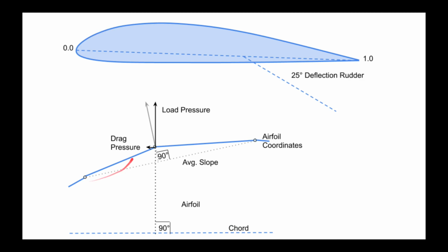And so that's what these little circles are representing, the positions of the individual points on the airfoil, and that would be something like up in here. And those pressure values we have are at those coordinate points. Like, for example, this gray line I have here, this would be the pressure value at this coordinate, although we don't have an angle for it. We just have a magnitude. What I need to do is figure out the angle at this spot.